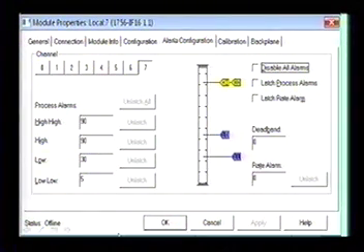And then we went over the alarm configuration. We set the high-high to 90, the high to 90, the low to 30, and the low-low to 5. And we know we can drag these up and down, right? And we can change these values. And if we hold the shift key down and drag them, we get whole numbers, not 90.5 or whatever you want. And remember, that can't be checked right there, because if you check this, then on this whole screen you don't see any of these alarms. Okay?